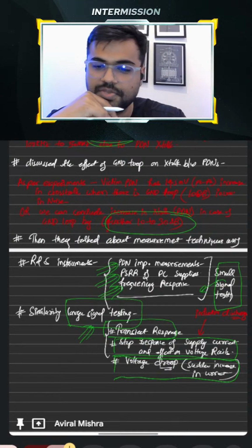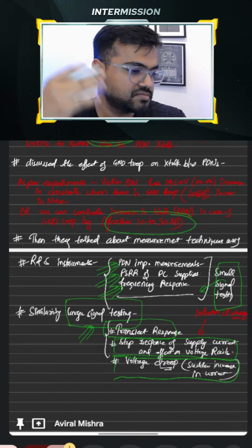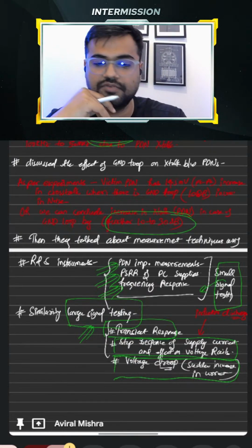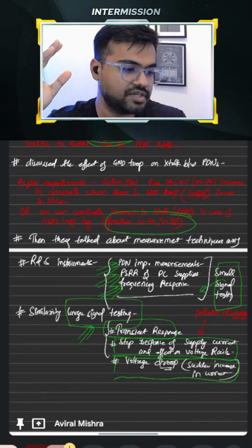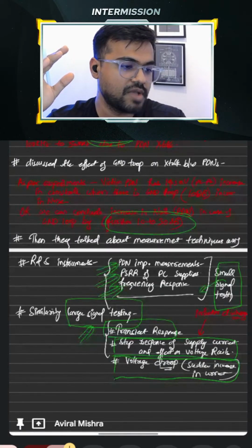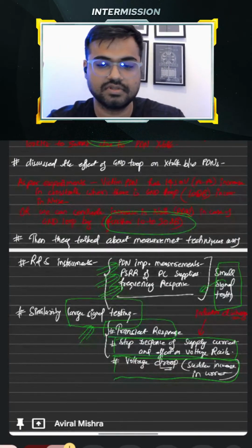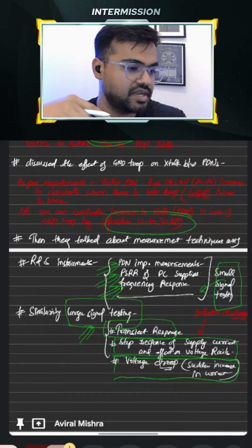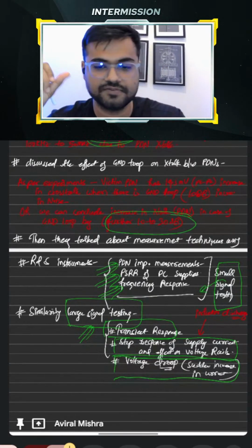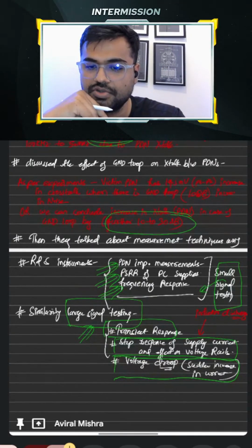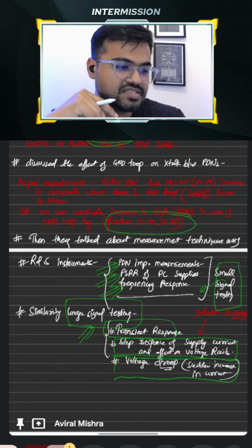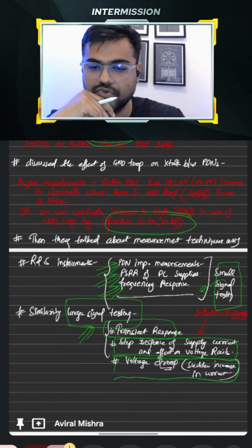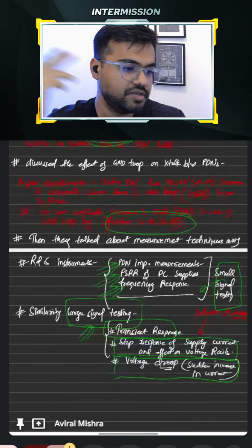Let's say we are probing our DC-DC converter, a buck converter, and suddenly we increase the current of the buck converter, let's say from 0 amps to 5 amps. Just put some electronic load and turn it on at 5 amps. Due to the sudden increase in current, we'll see some crazy ringing on the voltage side. So we call it voltage droop.